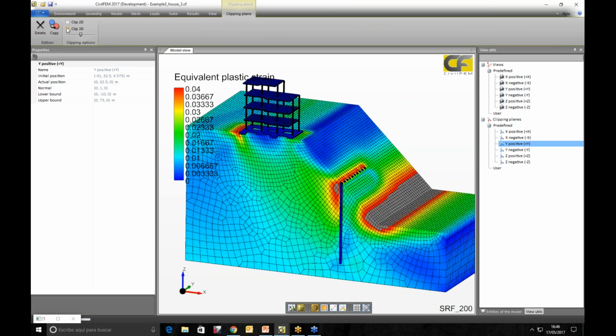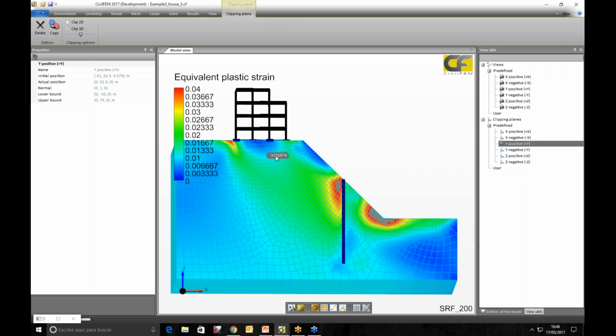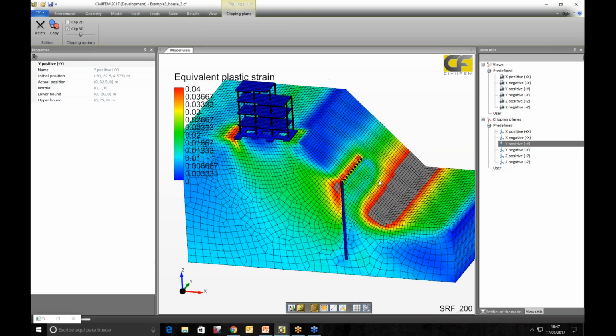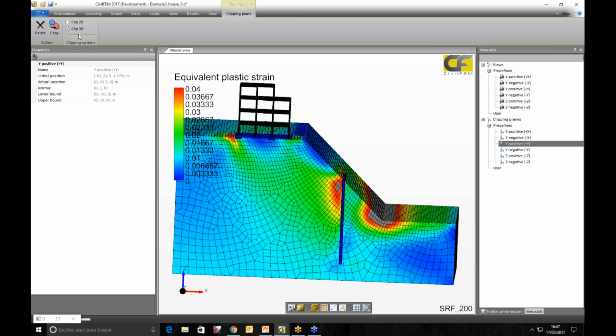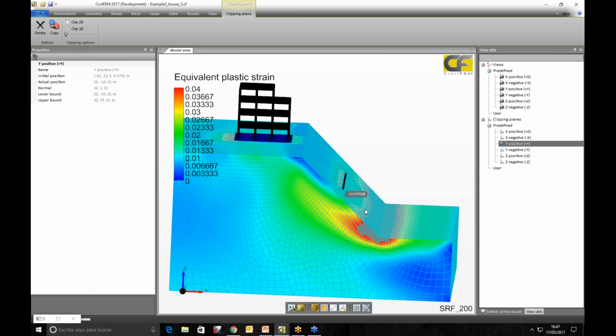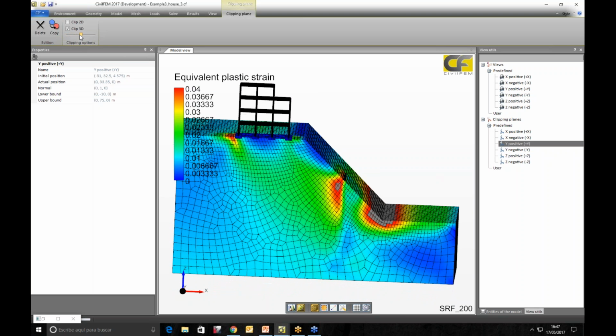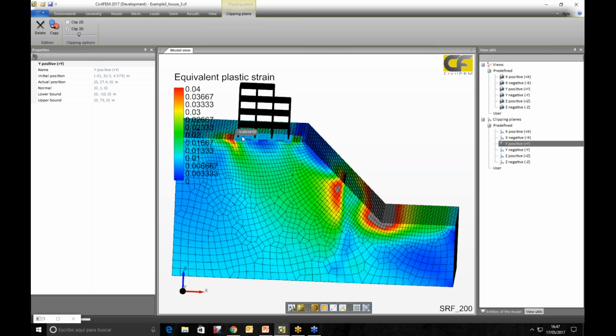we did with the previous model, we can see now that these piles are cutting my yielding zones and are reducing the displacements. But well, yielding is happening after the piles. When the piles are finished, we have the yielding, the sliding surface. And well, here the others, due to the building, that due to the piles, they don't connect to the other